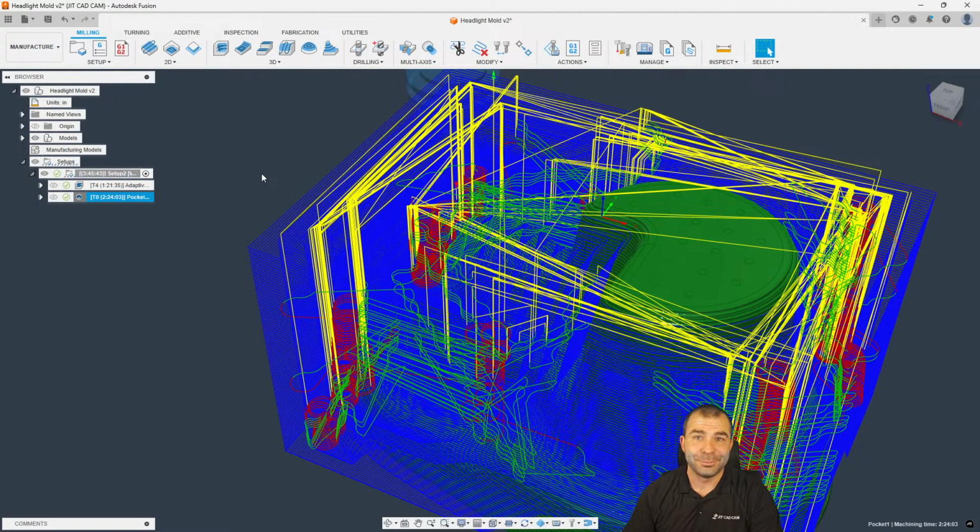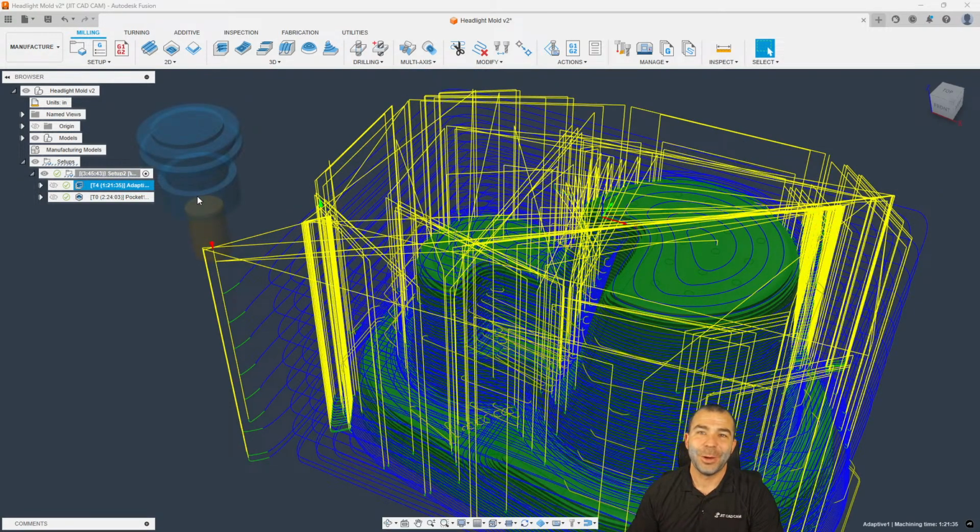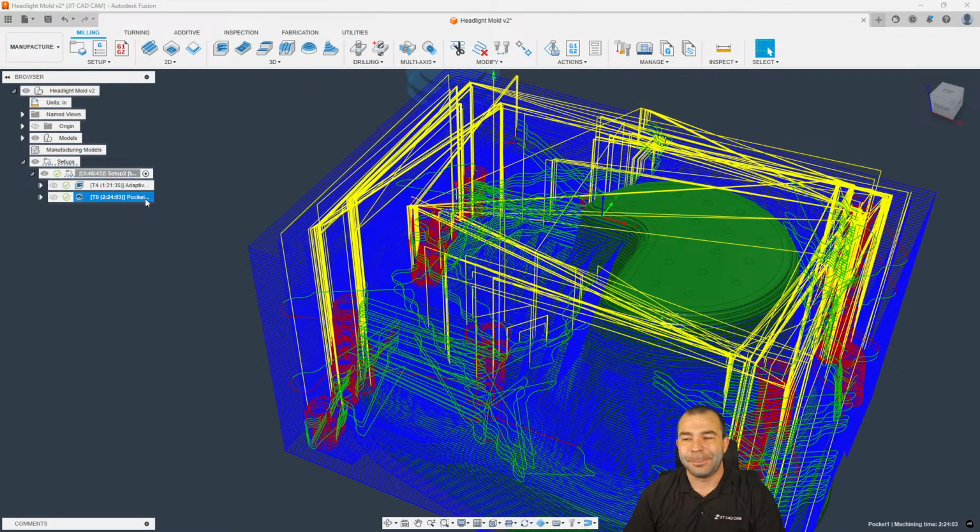I know in the world of machining, most machines wouldn't be able to handle a 1-inch cutter as well as you would think because they lack torque. Now, some of you are on some pretty big machines out there, of course, but as you can see, the pocket clearing side of things, again, it's less torque on the machine. You can feed it much faster, and you can make up time in speed. Again, it's a case-by-case scenario, in my opinion, TC. Hopefully that answers your question.